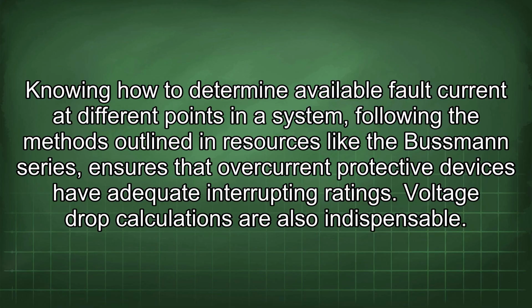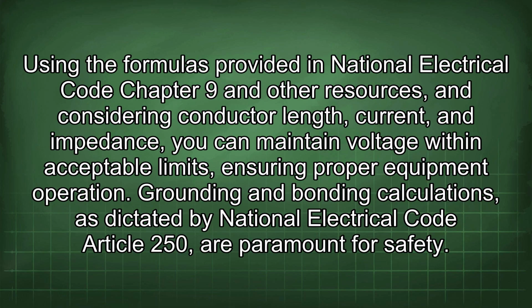Voltage drop calculations are also indispensable. Using the formulas provided in National Electrical Code Chapter 9 and other resources, and considering conductor length, current, and impedance, you can maintain voltage within acceptable limits, ensuring proper equipment operation.